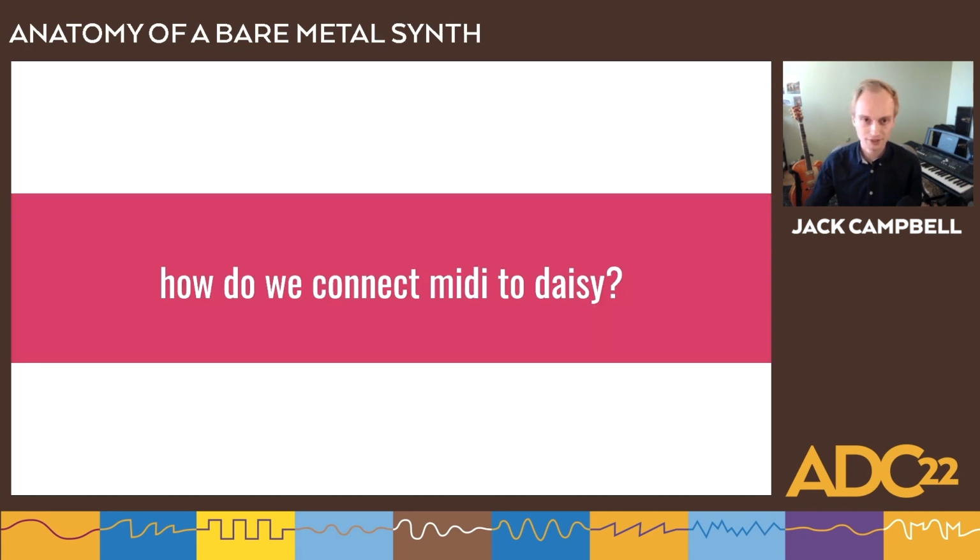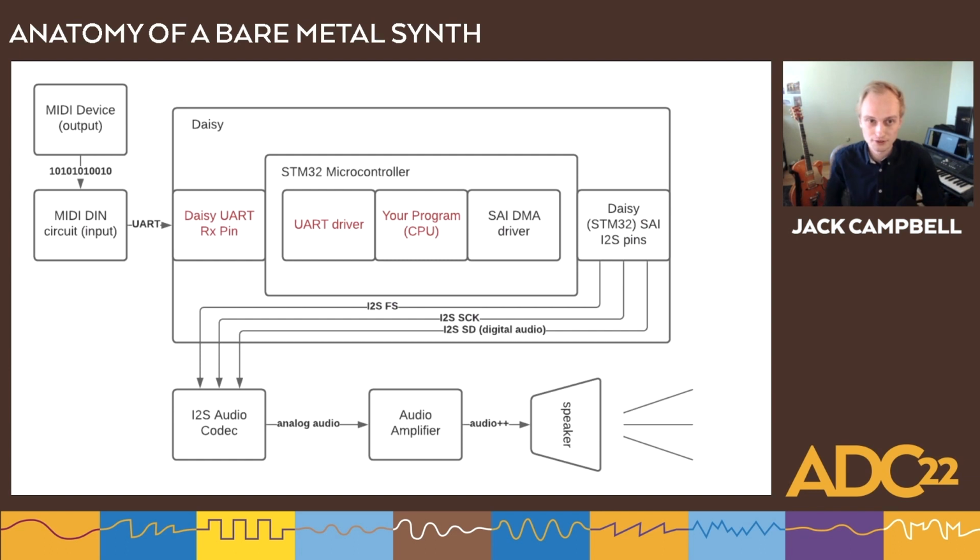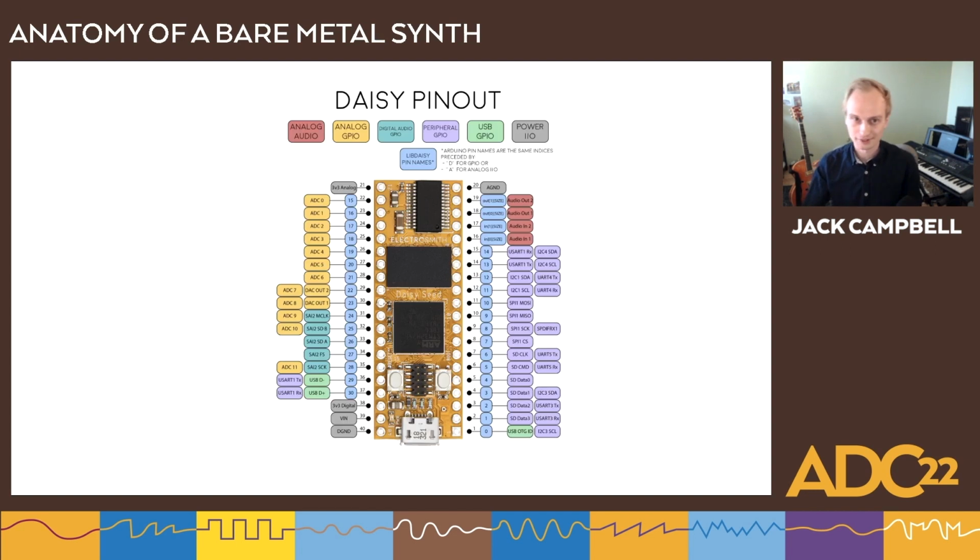But in our case, we are going to use a UART RX pin. I forgot if I mentioned it yet, but you'll often see RX as shorthand for receive, and TX for transmit. So in our application, we will be receiving UART and transmitting, TXing, audio.